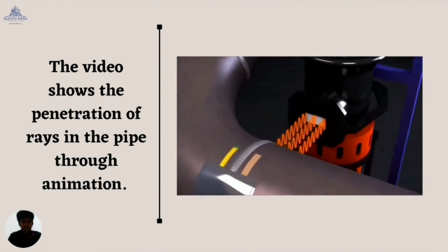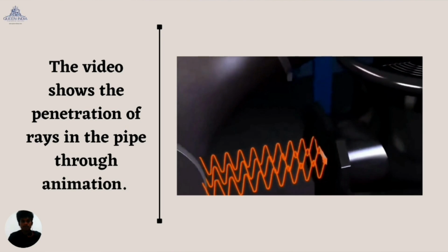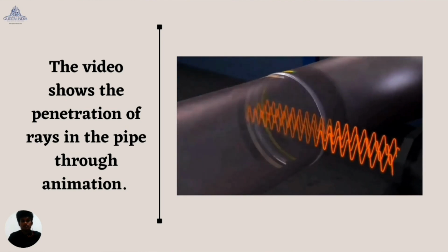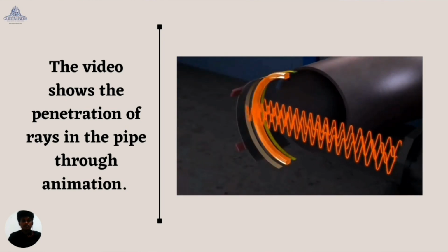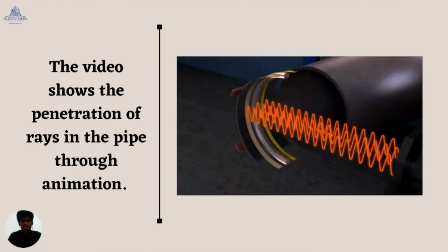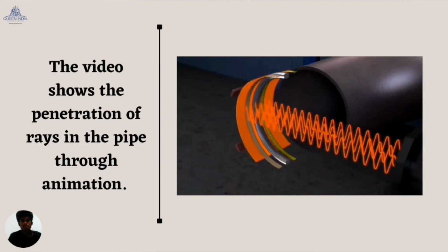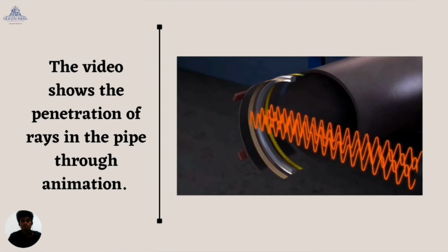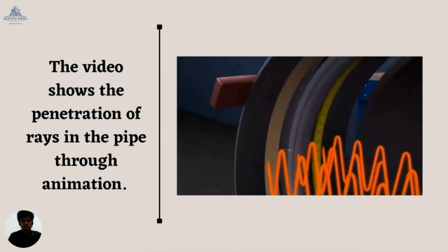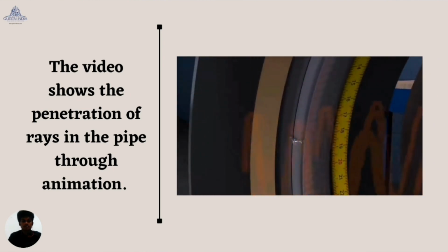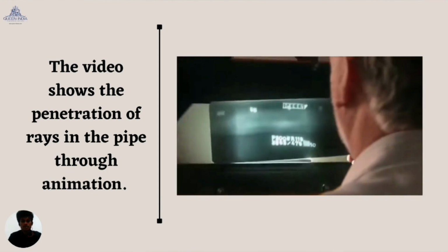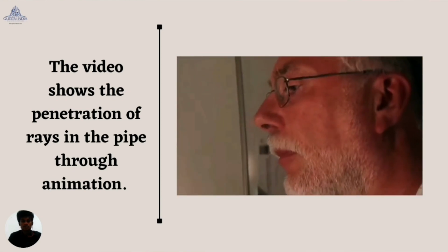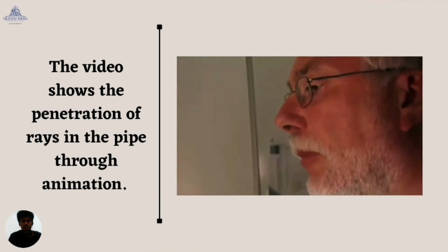The X-rays go through the material and generate a radiographic image on the film or imaging plate once processed. Now the experienced eye of the examiner interprets the image and he can determine the quality of the inspected object and whether it meets the standards.